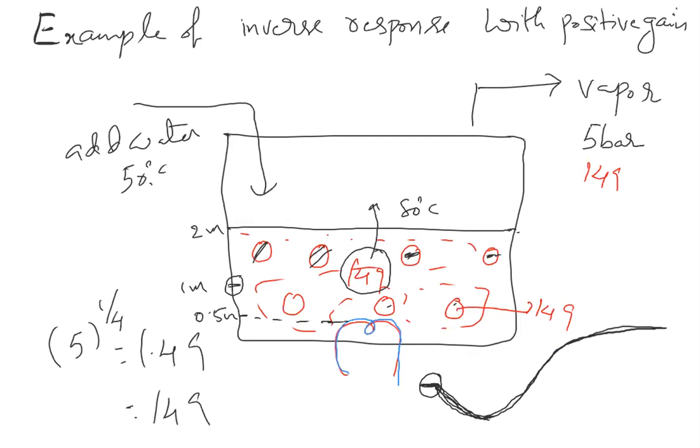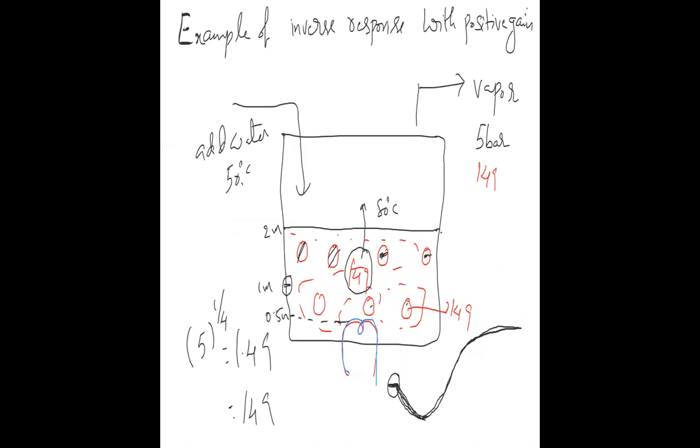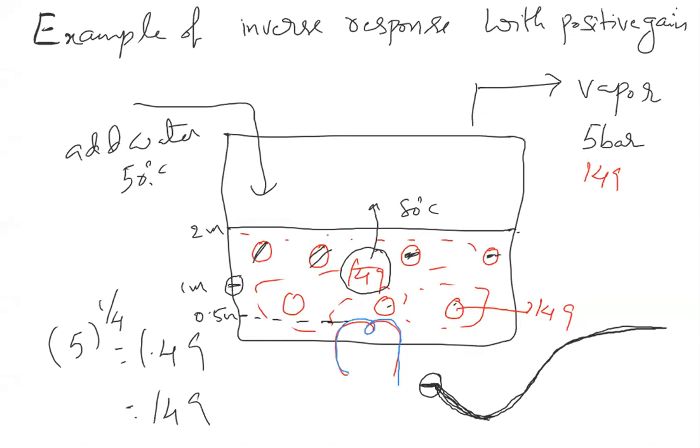When the boiler trips, this steam is received by many plants. In the MEB I told you what is the use of steam. Because the steam is the one which is actually generating heat for most of the heaters. Suppose the boiler trips, it starts from 2 meters. Suppose this bottom comes below 1 meter, then the boiler will trip and the plant will trip. That is why when the level is going down, you have to be extremely careful.